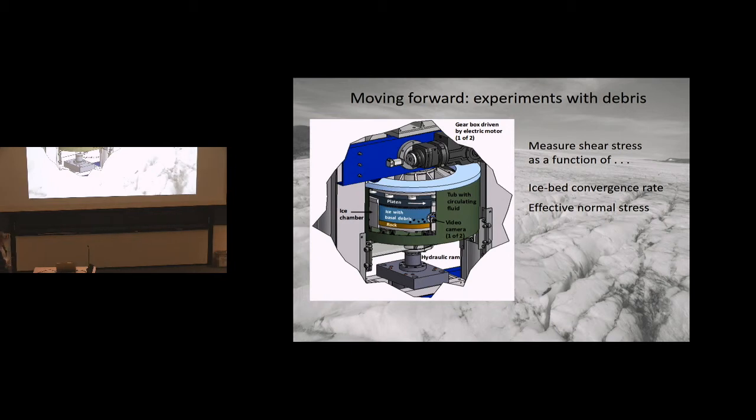And the reason we think is that we develop, first of all, cavities beneath these particles that are filled with water. And the water, although it's allowed to drain off the edges of this bed, ultimately the water pressure in those cavities ends up being commensurate with the ice overburden pressure. And so when we increase the total normal stress on the ice, the water pressure increases as well. And that reflects the need to evacuate this water produced by melting around these particles out along the bed surface. So the hydraulic gradient increases, and that basically nullifies the effect of the increase in total stress.